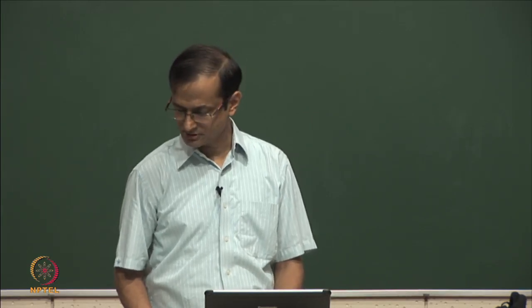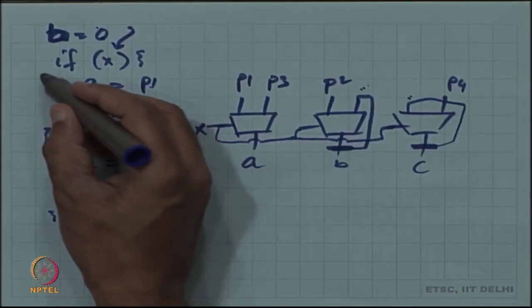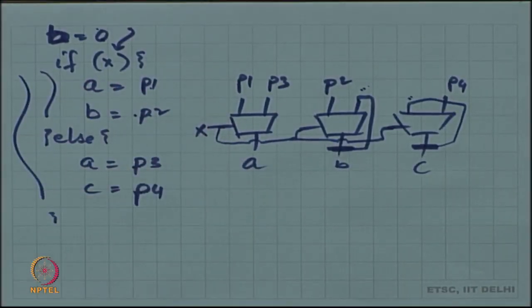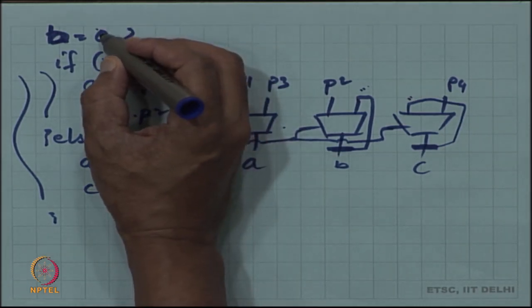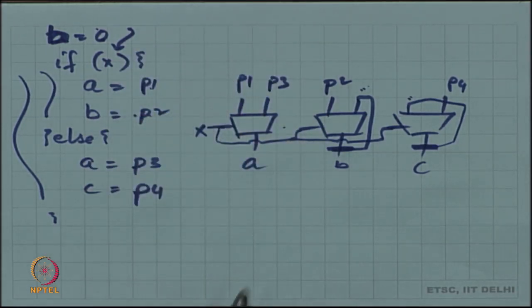Yeah, so these multiple paths here through the then and through the else is what caused the inference of the mux, but the absence of an assignment in one of the paths caused the memory to be inferred. But if you are sure that it is a combinational circuit that you have in mind, then whatever the assignment is, it could be a more complex function, but that function goes as the other input to the mux, and there is no need for the feedback to be introduced in the mux.